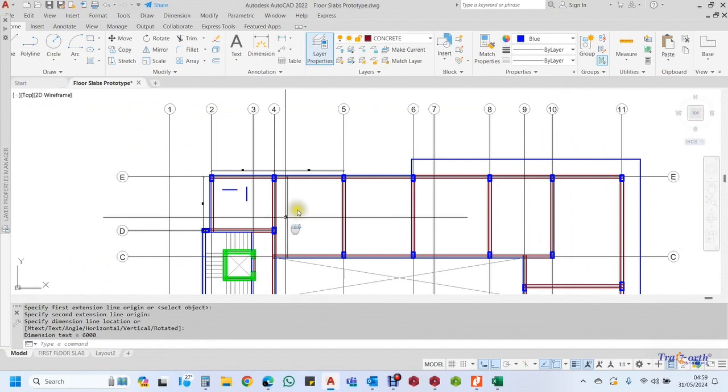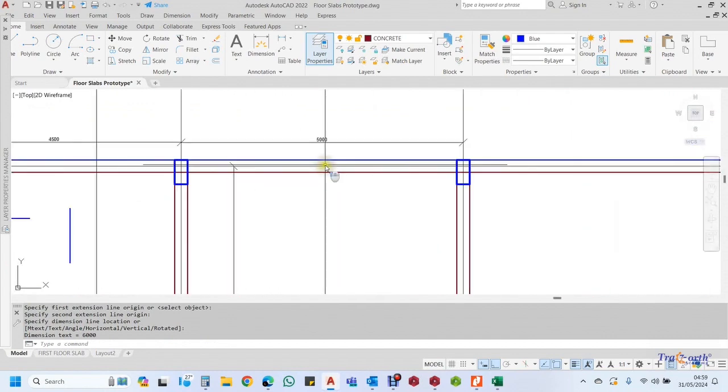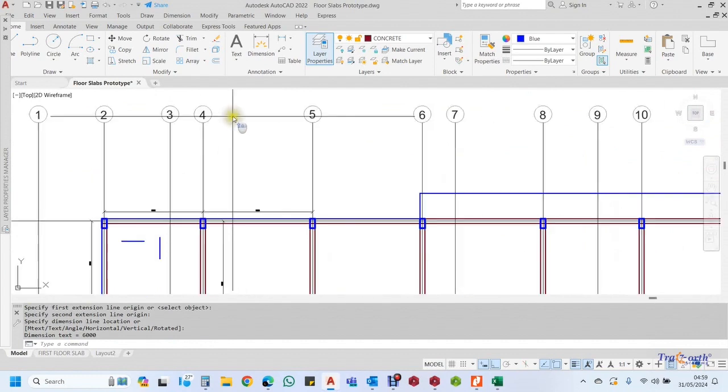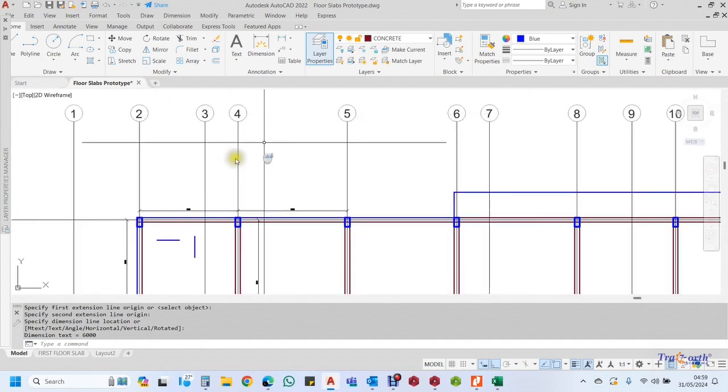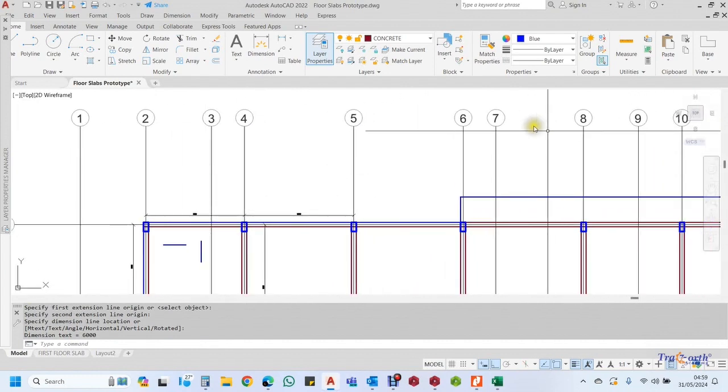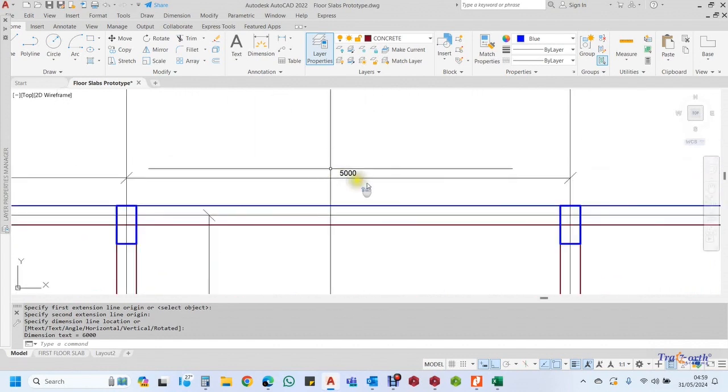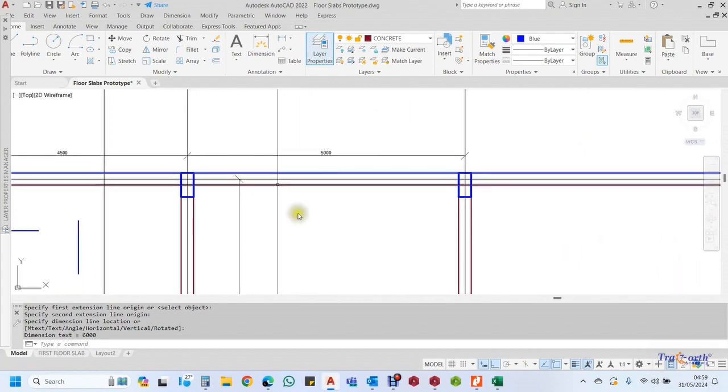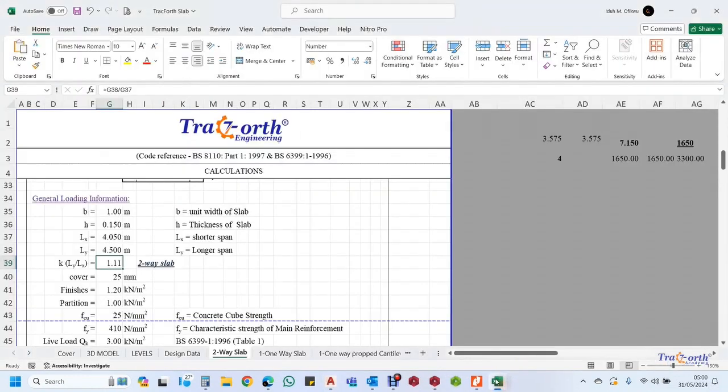So then we'll now measure the full edge of the slab. So in this case now, the table has turned. That means from grid line 4E to 5E, it will become our short end. So please, you must pay attention to this.